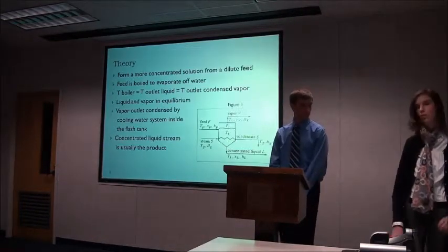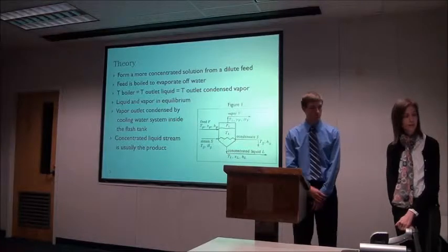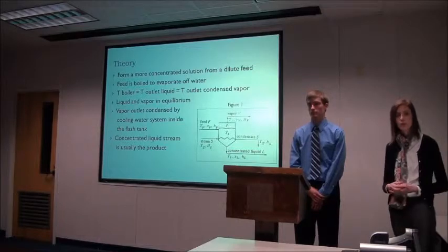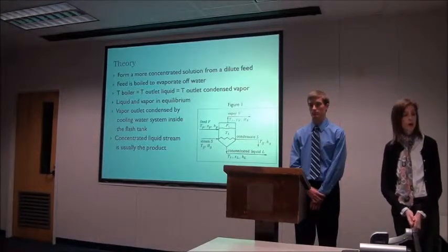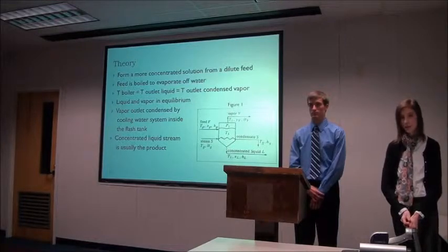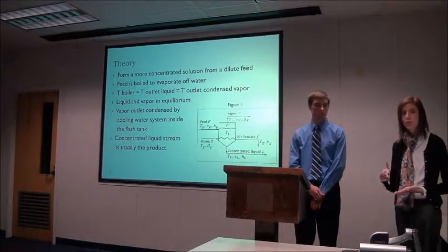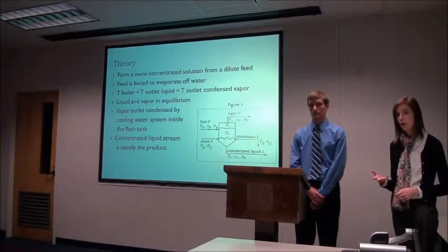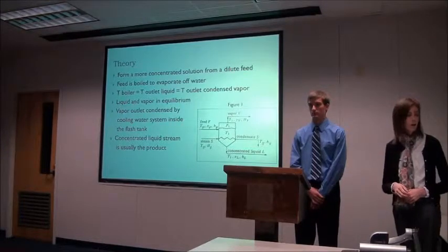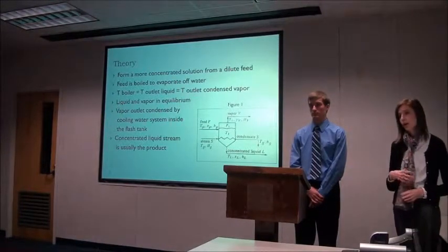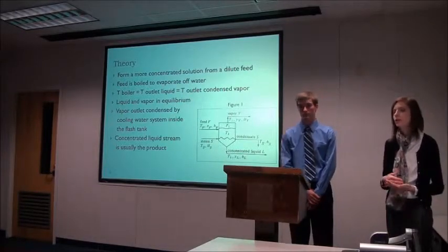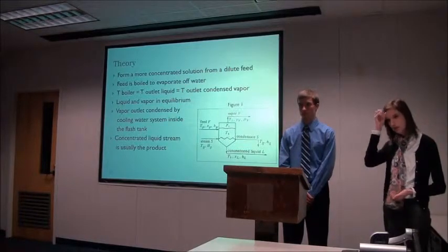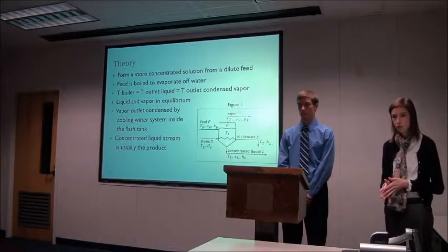I'll continue now with a little bit of the theory and the background of a single effect evaporator. As Scott alluded to earlier, the purpose of a single effect evaporator is to form a more concentrated solution from a more dilute feed. In this case, pure liquid water was our feed, and so our two product streams were liquid water and the vapor condensate water. The feed was boiled to evaporate off water, but normally you would have some other solvent or some other concentration, maybe ammonia or something else in there, that you would be making a more concentrated solution.